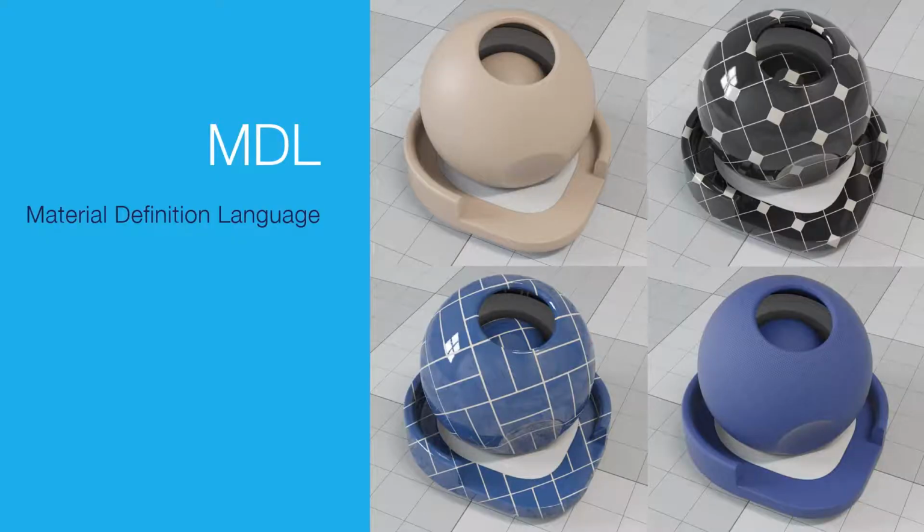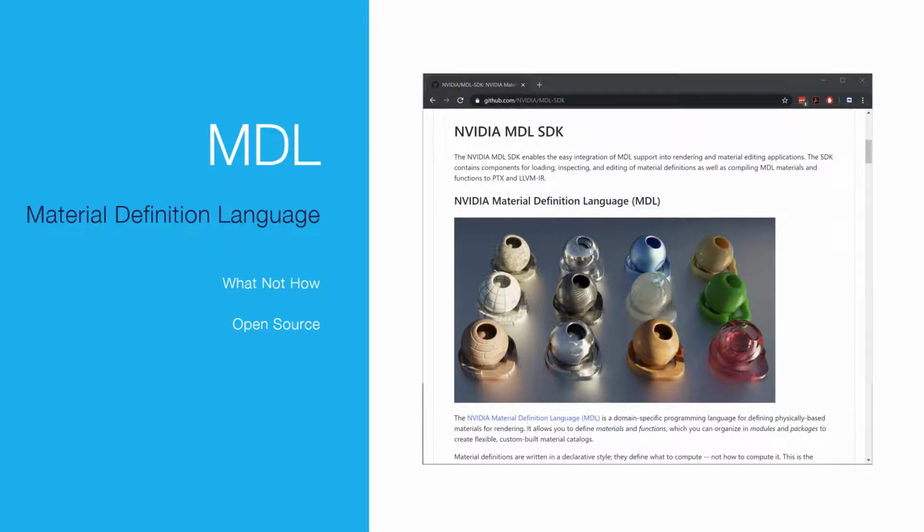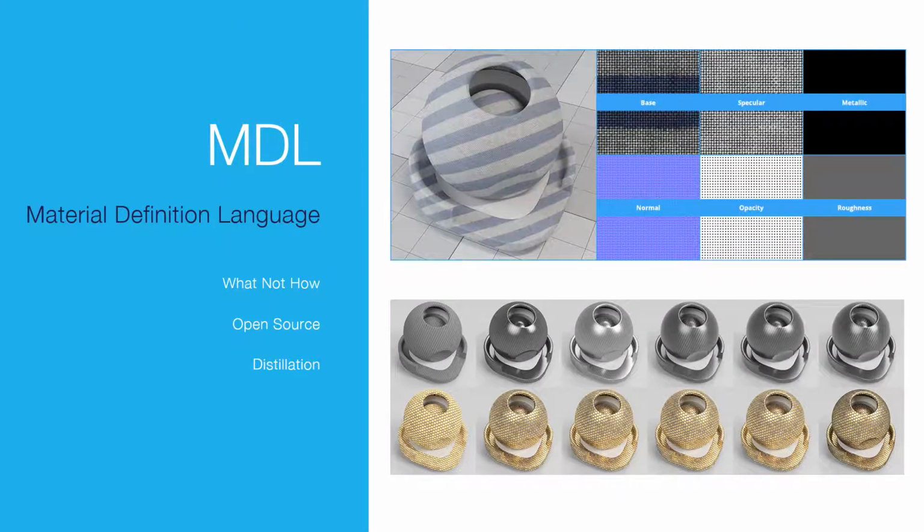The use of Iray for rendering brings with it the adoption of MDL, the material definition language. Appearance is something that's often overlooked. MDL offers a way to represent virtually any material appearance in a standard format. It describes what to render, not how to render it, and this is important for efficient execution on the GPU and ensuring physical accuracy. It's now open source and you can use it in your applications, and it has an interesting feature called distillation. This allows you to take a material and simplify it into a target model that you can use in your application that doesn't support MDL.